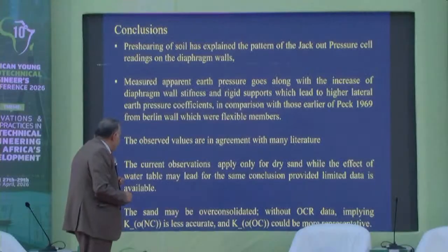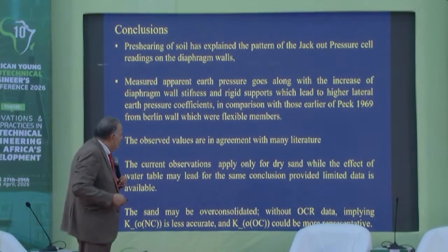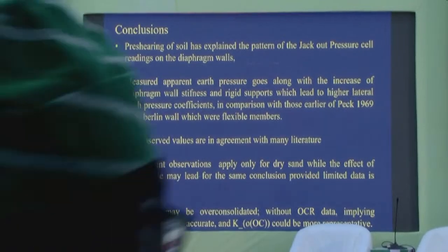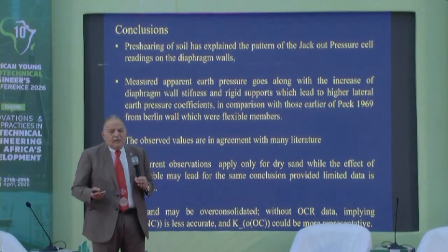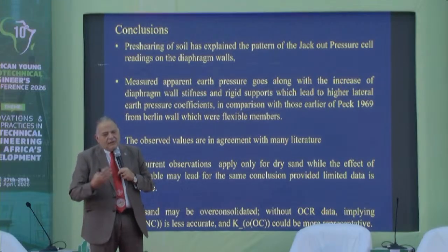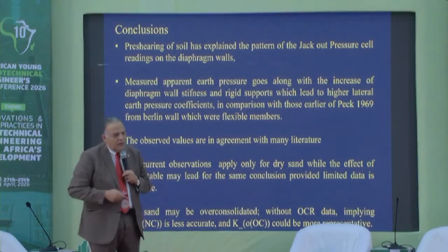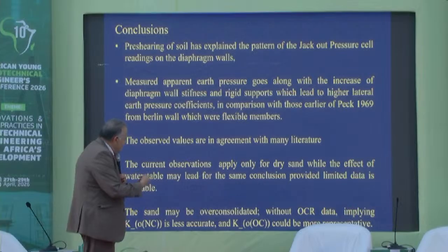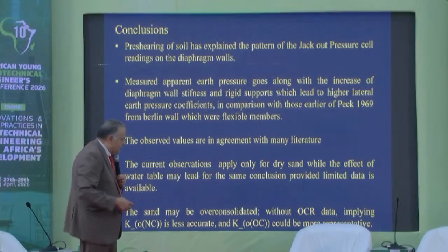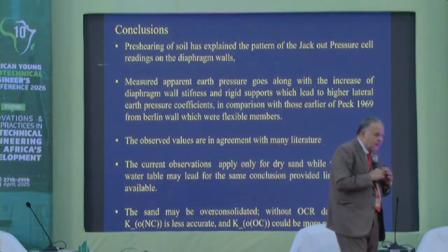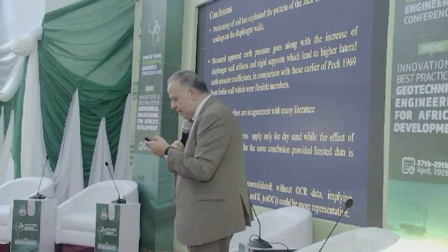The observed values are in agreement with many in the literature, and the current observations also apply, and this is something to say, because the sand that we have was dry sand. So maybe if we have wet sand or saturated sand it might not, but I think it will be similar. Again, we have to mainly think of over-consolidated, not normally consolidated, if we are going to use this normalized way of the apparent earth pressure.